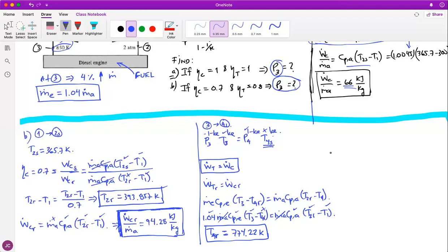Well, okay, now what? With this information, you can go back over here, well, no, because out of this equation, you will get some isentropic information. And this T4R is actually an actual temperature outside of the turbine. So maybe it's not a good idea to put it over here, because out of this, you are actually waiting for something that is isentropic. Therefore, you need to use this.